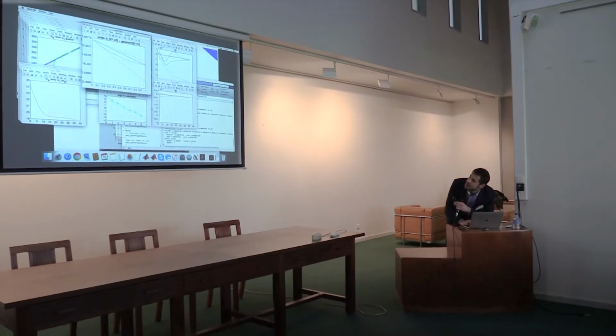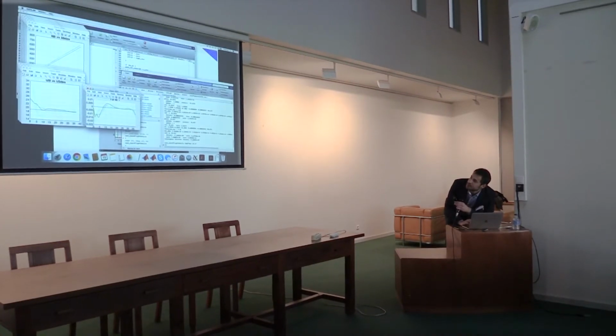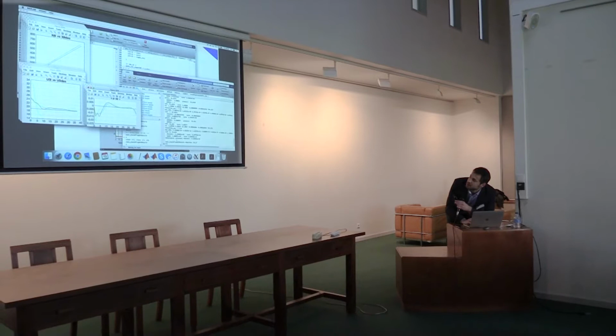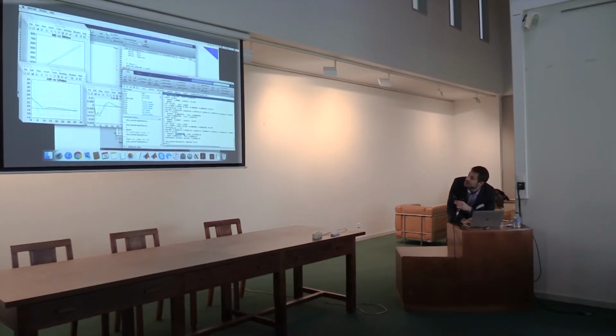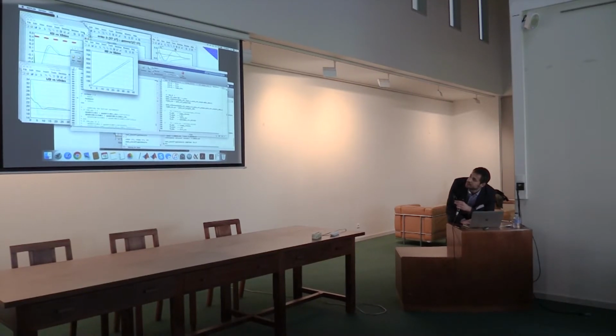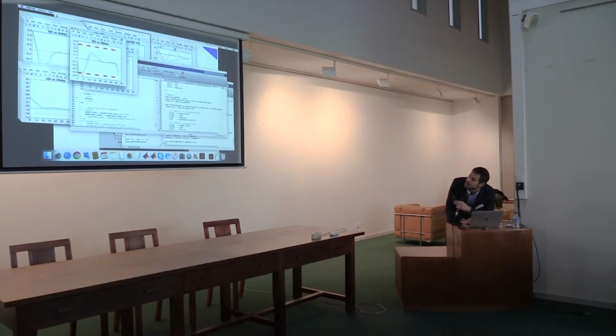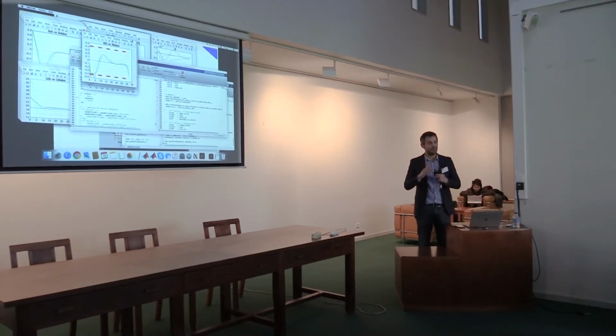Yeah, it looks like the second order is working right now, so we should go faster now. So what happened here is that we found a local minimum of our system with high precision. And these are the trajectories of our UAV at each step. At each step, this is important, we compute a trajectory. So actually, we can perform this trajectory for our UAV.